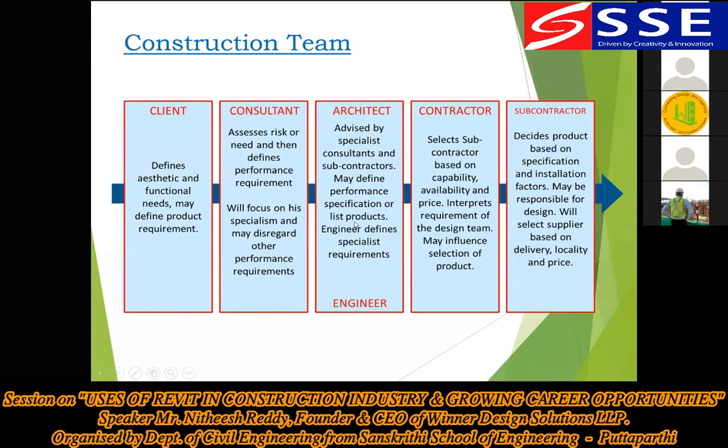If I start talking about a construction project, first what you require is a plan. You start from scratch with a plan. The plan will include all the drawings like architectural drawing, structural drawing, electrical, plumbing. After finishing all this, there will be something called shop drawings. Shop drawings will include all the detailed drawings with complete dimension details.